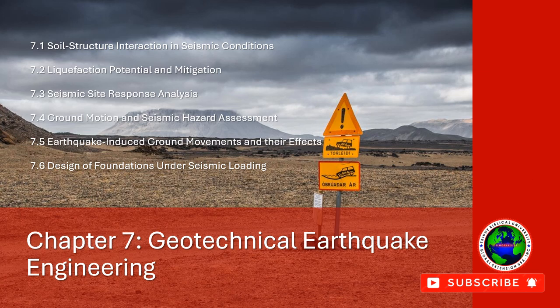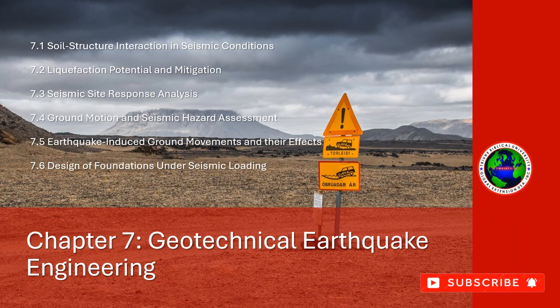3. Field observations. Post-earthquake field observations, including the identification of surface ruptures, sand boils, and lateral spreading, can provide valuable insights into liquefaction behavior and help validate laboratory and field tests.